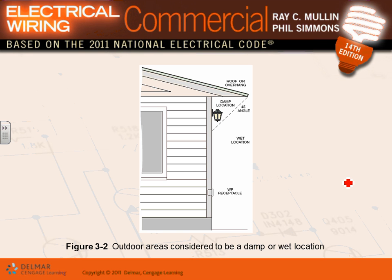Area is considered to be a damp or wet location. When you put your fixtures or receptacles or anything right underneath the canopy here, this will be a damp location. Obviously, if it's right in this area, that's your wet location. When you put your receptacle there, they have to be in an enclosure rated for wet location, with an in-use cover, and they have to be weather resistant, and they have to be GFCI.